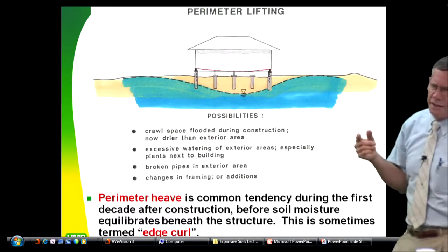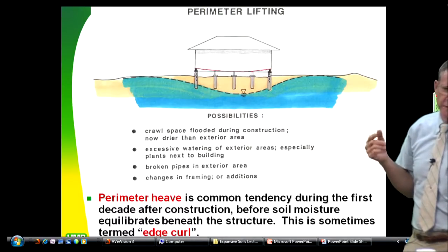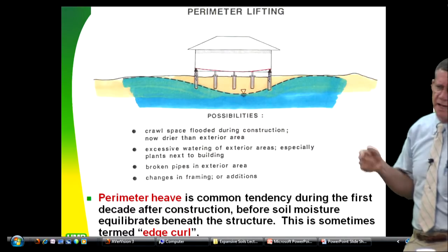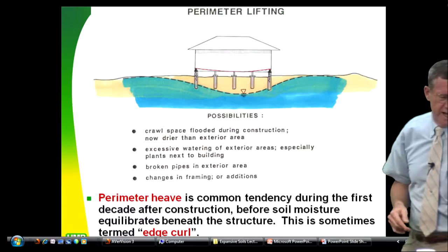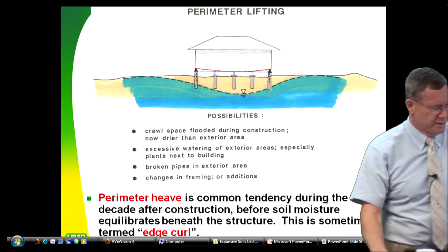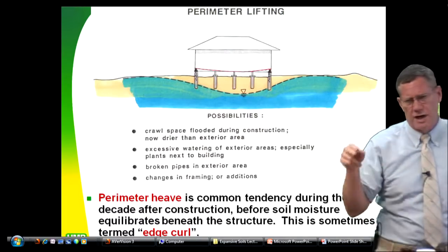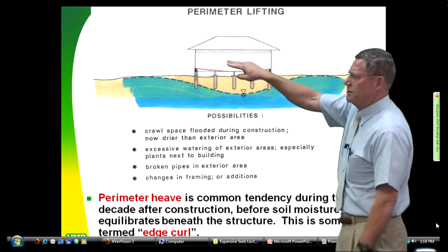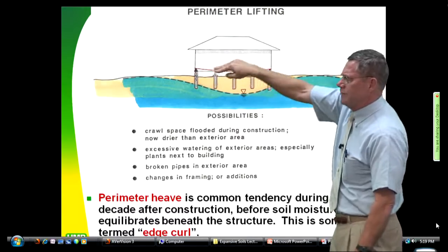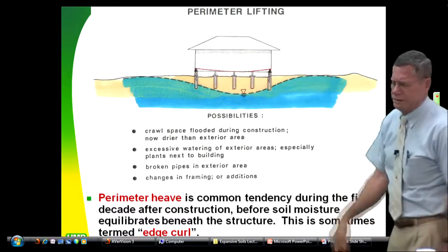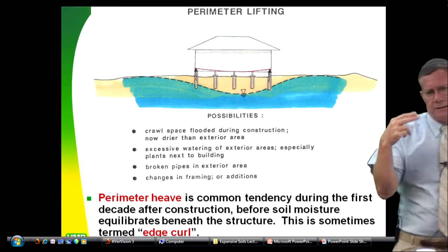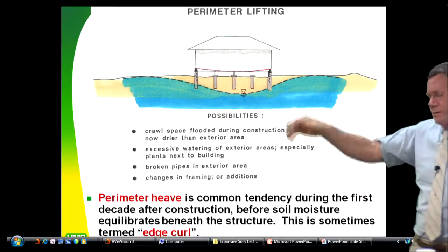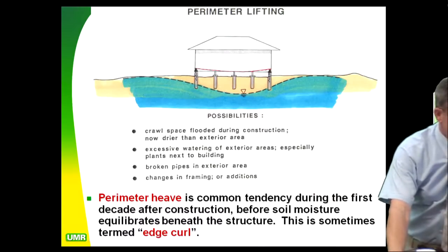And these are actually accounted for in the International Building Code in Chapter 18 and in the PTI manual, the Post-Tensioning Institute manual for post-tension slabs on grade on expansive soils. So you actually have to design, the controlling parameters are edge curl and interior doming, because you're going to get a moment change when you go to interior doming later. So this thing's going to end up having a W kind of shape, and as long as delta L over 180 isn't exceeded, you have tolerable tolerances for that bending.